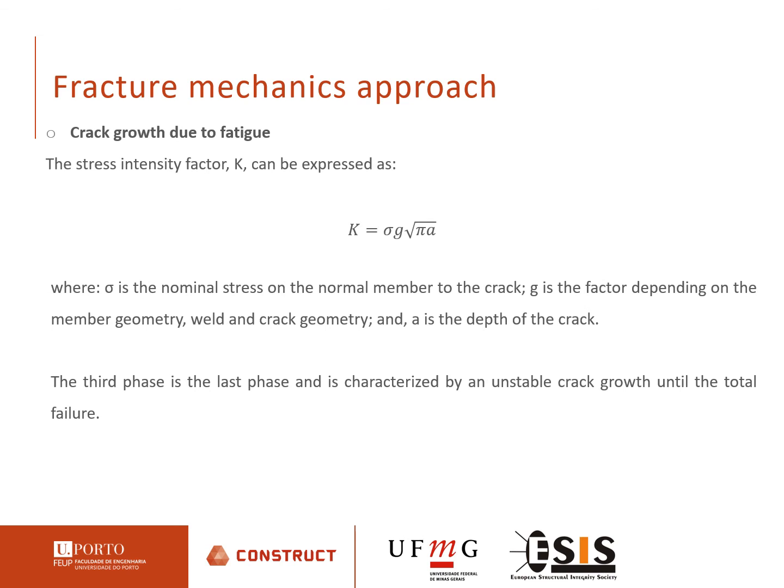The stress intensity factor can be expressed as displayed here, where this variable is the nominal stress normal to the member's crack, G is the factor depending on the member geometry, weld and crack geometry, and a is the depth of the crack. The third phase of the crack propagation is the last phase and is characterized by an unstable crack growth until the total failure.